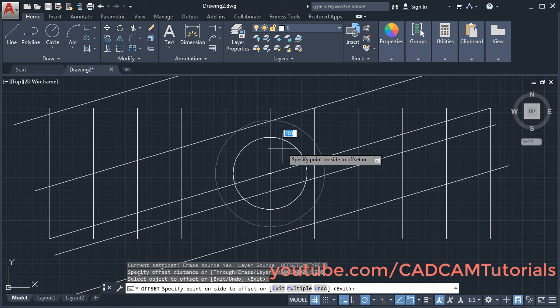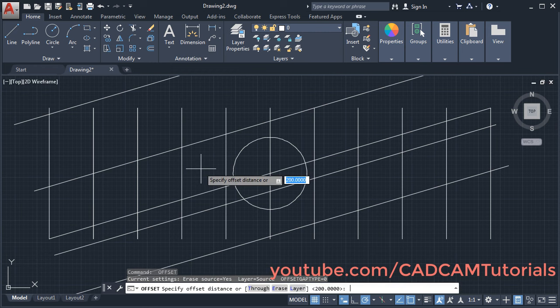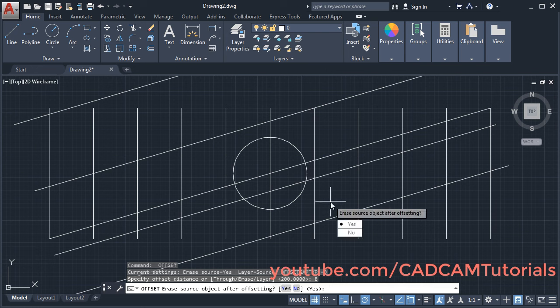Then click inside. Now our erase option is on, therefore that outside circle got erased. So at first we will have to turn that off so that it will not be erased. For that press enter. You can repeat the last command by pressing enter. Press enter, click on erase, then select this no option.